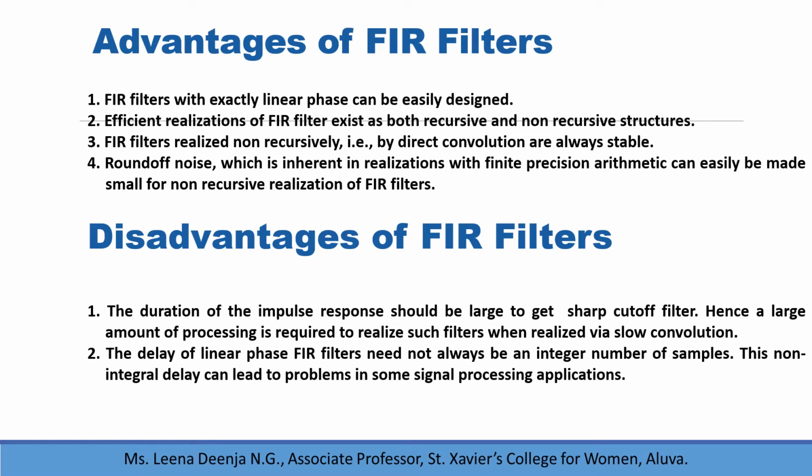Non-recursive means a system whose output at any time depends only on a number of present and past input values. Third, FIR filters realized non-recursively, that is by direct convolution, are always stable.